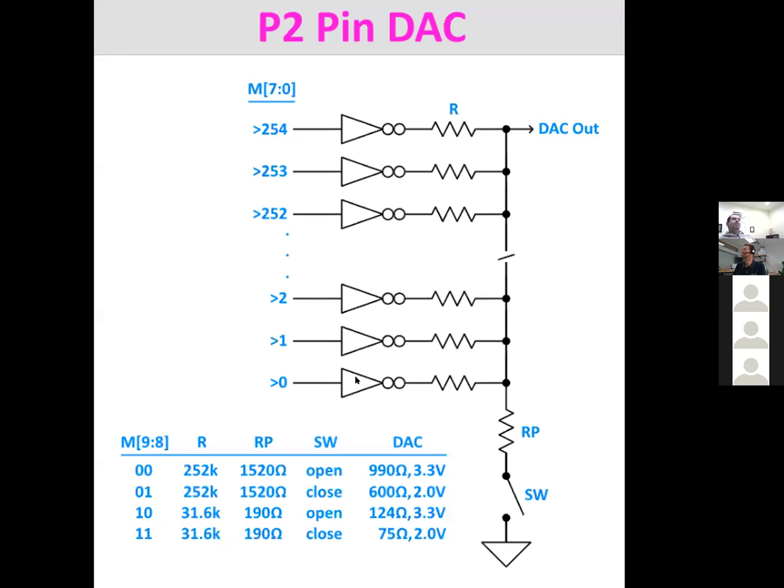And so the smart pin stuff can actually take any value and dither, it takes a 16-bit value. The top 8 bits drives the DAC directly, and the bottom 8 bits is added to in some fashion, either with random noise or with a counter, so that we get a PWM out, and then that causes the DAC to transition to the next value up periodically. And I have a little demonstration of how that works today.